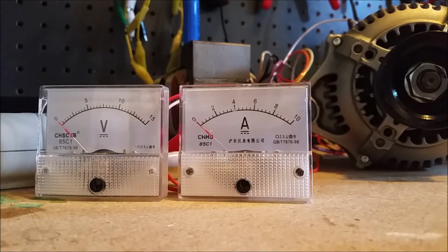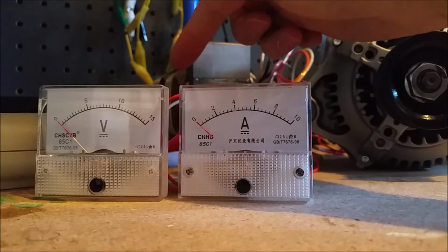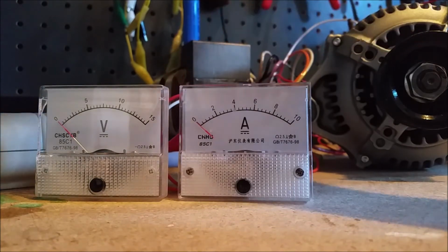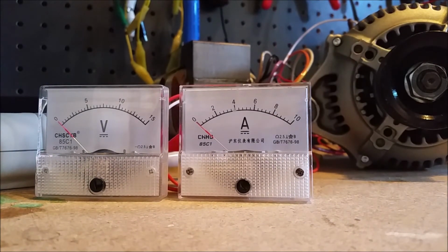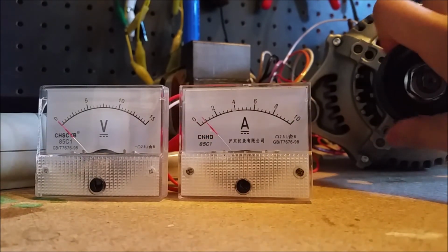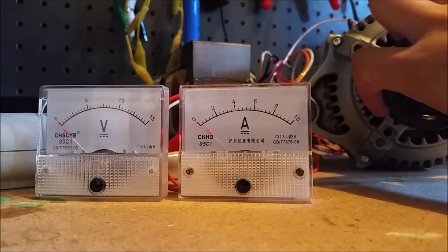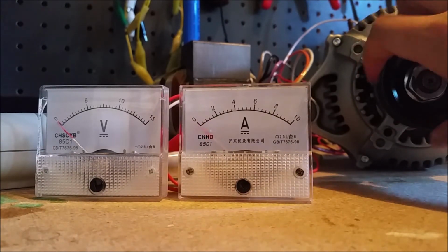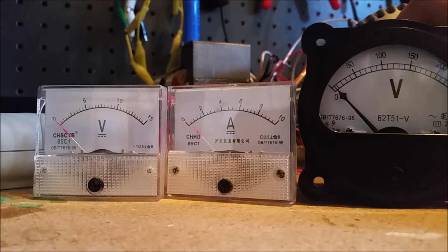But let's get back to the power being generated. Right now the ammeter is hooked up between phases B and C, and the voltmeter is hooked up between phases C and A. And of course these aren't to measure voltage or amperage, they're just to show you the different waveforms. And so if I turn the generator, you'll see that while both needles rise and fall, they do so out of time from one another. And what that means is that they're out of phase. And if I had a third meter that was more appropriately scaled, then you'd be able to see that all three phases would do so.